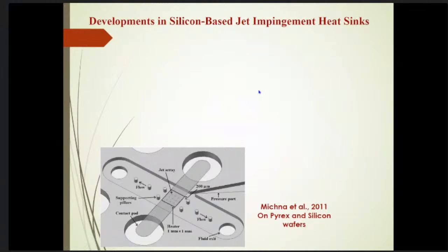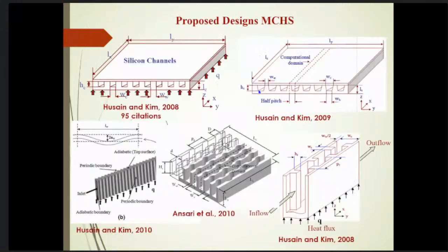Another constraint in the chip is that the temperature throughout the surface of the chip should ideally remain uniform. So what happens when we have the channels grouped on the chip surface? The coolant enters from one end and leaves at the other end. Obviously, when the coolant is entering the channel, it has the maximum temperature difference for the heat transfer to take place.